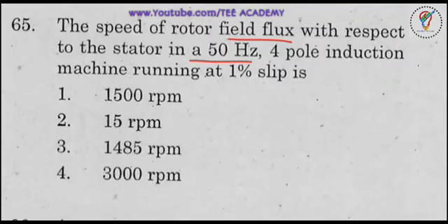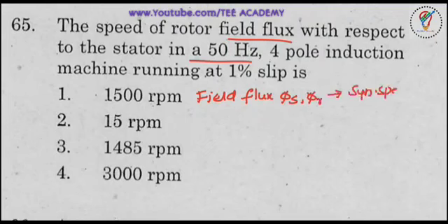Here they are asked to find the speed of the rotor field flux, not the rotor speed. The actual physical rotation of the rotor is different; rotor field flux is different. Generally this rotor field flux rotates at synchronous speed. Remember, both the stator field as well as the rotor field flux rotate at synchronous speed. The rotor physically rotates at the rotor speed, Nr.